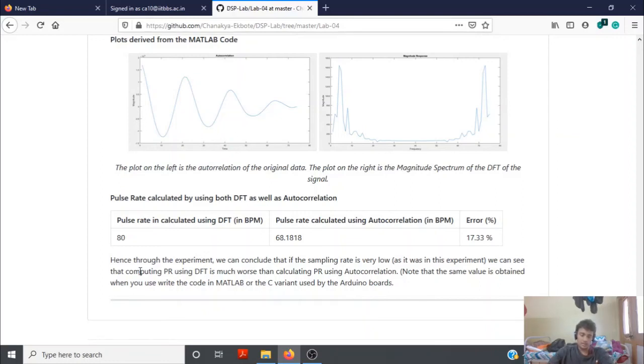And the reason for that can be thought of as, in an autocorrelation function, irrespective of what you do, you're just multiplying two signals. You're not decomposing the signals into anything, right? You're just multiplying. And inherently, if you're just multiplying signals, if there is a particular repetition, then that repetition will get captured when you do the multiplication, irrespective of whether some data points are lost or not. And that is because by discretizing the signal into data points, you don't mess around with the periodicity of it. You're just maybe reducing the point size, and hence the inherent time period of that signal will not be lost.